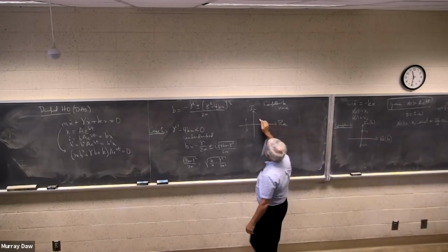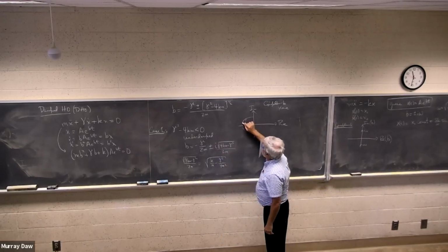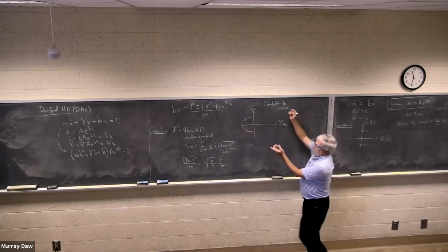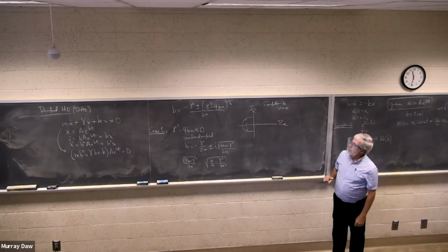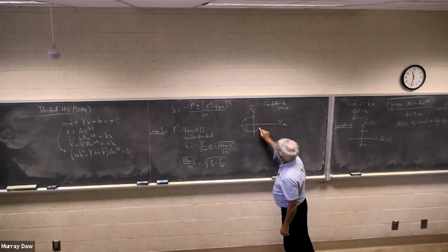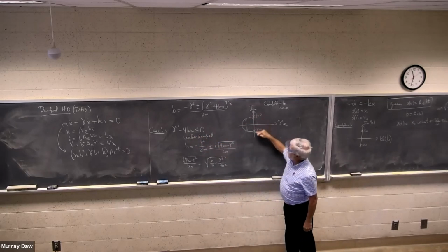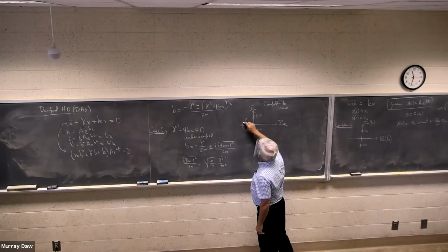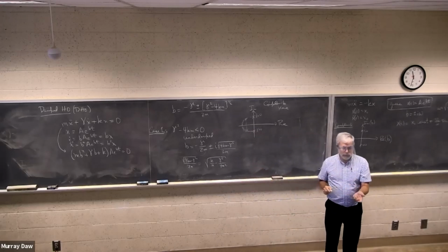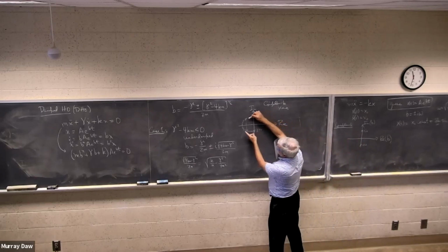So to compare them to what we were getting before, these are coming down like this as a function of gamma, as a function of the damping. These are coming down, approaching the real axis, on the left, as a function of gamma. So here's where gamma is 0. We've got these two roots. And then for gamma less than root 4 km, it's someplace along this arc. Two of them. Maybe I should dot this so you can understand that there's a range of possibilities, that you can control the damping on the system somehow. Increase the damping, then you're moving the roots down this way.